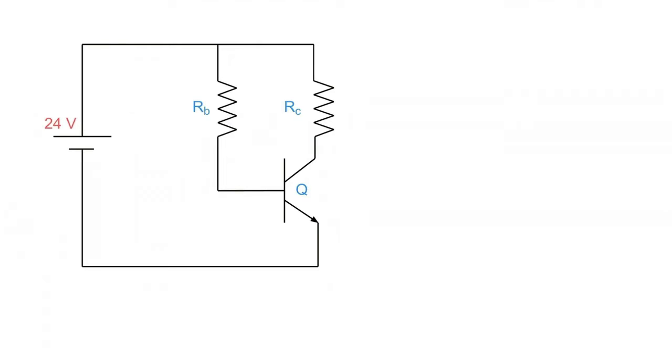A transistor is basically like two back-to-back diodes. So what we're looking at here is a diode here that will be forward biased. And what is the volt drop across a forward biased silicon diode, you ask? It is 0.7 volts. So we will have a 0.7 volt drop from the emitter to the base always, if it's silicon. If it's germanium, it's 0.3.